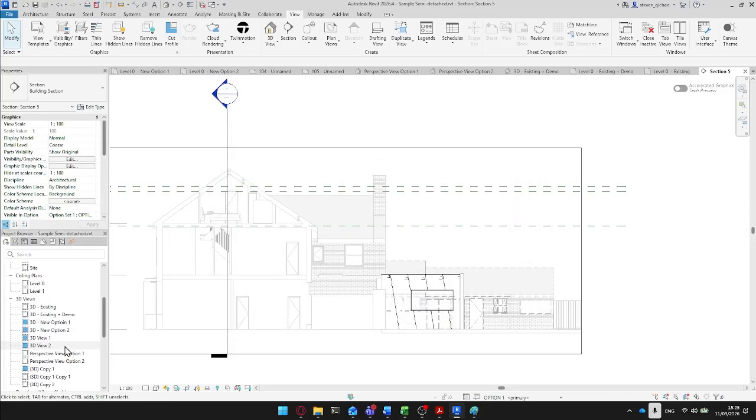Again, the main advantage of working this way is that in practice, you are always going to show the existing, always going to show the demolished, always going to show the design options. Working this way makes sure that if you change anything anywhere, everything's coordinated. You're not like on a CAD drawing or in Rhino, where if you're making different versions on separate drawings, you have to update something here and update it across every single layer.